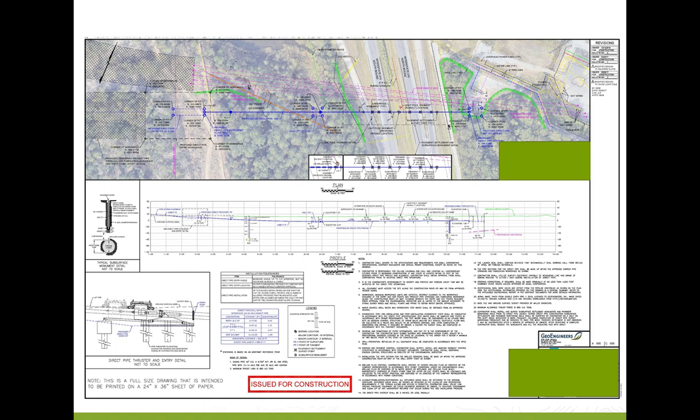This is an example of more of a minimum length and depth crossing, similar to what you might see out of a microtunnel, a curved microtunnel. It's a 3-degree launch angle with a 4,800 foot radius, and the pipe goes to an intermediate vault, which is right in the middle of the profile.